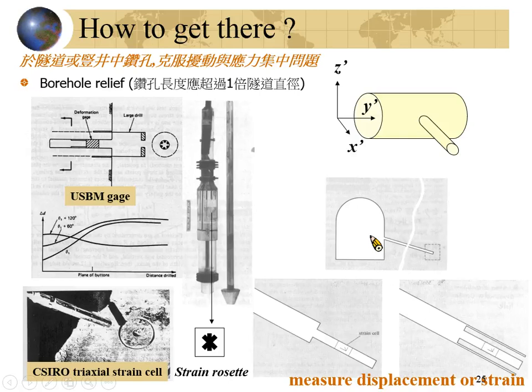In this case, this location is already away from the disturbance zone, about 2.5 times the diameter or 5 times the radius of the tunnel. Do you still remember this part? When the distance from the tunnel wall is large enough, the stresses sigma theta and sigma r will go back to sigma xx and sigma yy. It's around 5 times the radius, or 2.5 times the diameter.